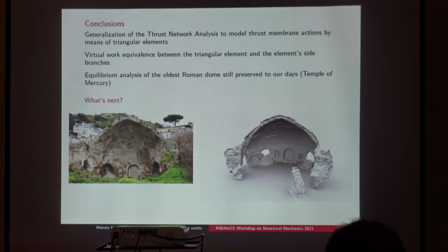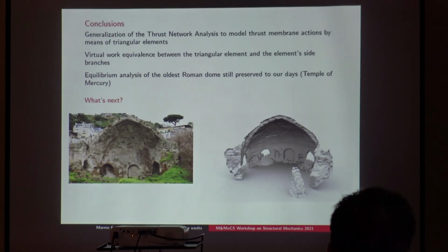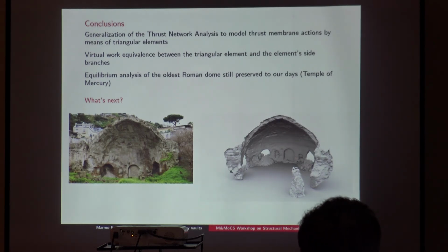However, the equilibrium equations are not enough to fully define the distribution of thrust values inside the vault, and so we are solving the problem as an optimization problem, because we have fewer equations than unknowns, but we also have some constraints. So this is why we are not using any stiffness information. We have the framework of the safety theorem of the limit analysis.